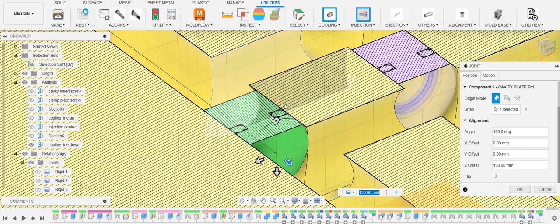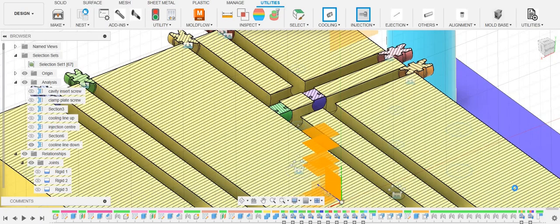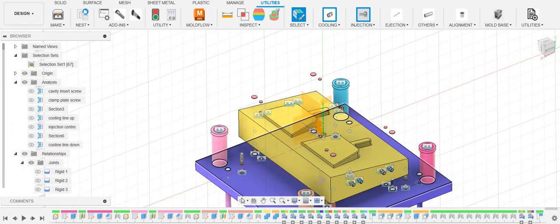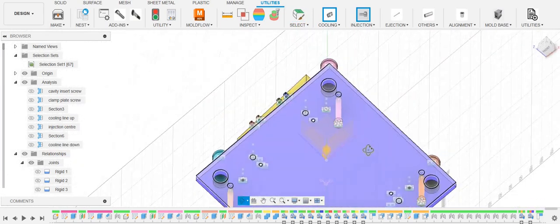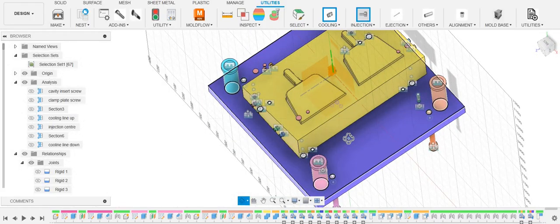It should be exported in STEP format, and if it's in STEP format, all the joint details and the assembly details will be deleted, but they will still retain their original position. So only if maybe another engineer wants to check something and inspect something, when he needs the assembly details, that's where that will have an issue.